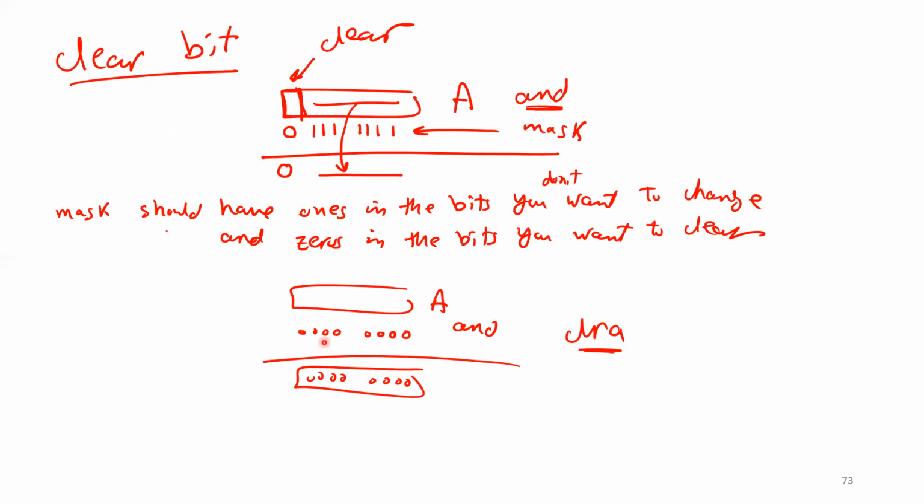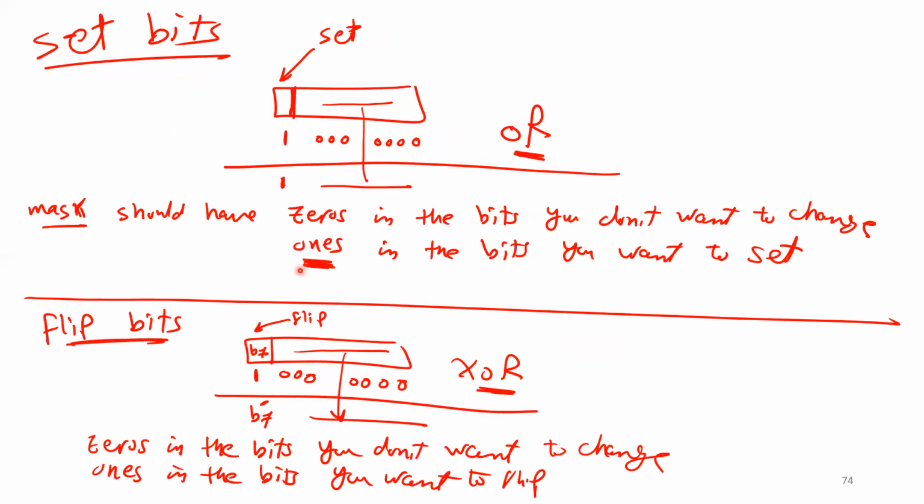So this is for sure. If I put 0, 0, 0, 0 and do AND, you actually clear all of them, so the result is going to be 0, 0, 0. This is similar to clear A. If you clear register A, we put 0 everywhere. Anyway, I'm just explaining. You may not need to do that. I'm just explaining that you can put more than one 0. Here is an example for one 0, and here an example if you put all of them zeros, whatever you want to do. Okay, guys, any questions? Nothing is new here, but maybe explained in an example.